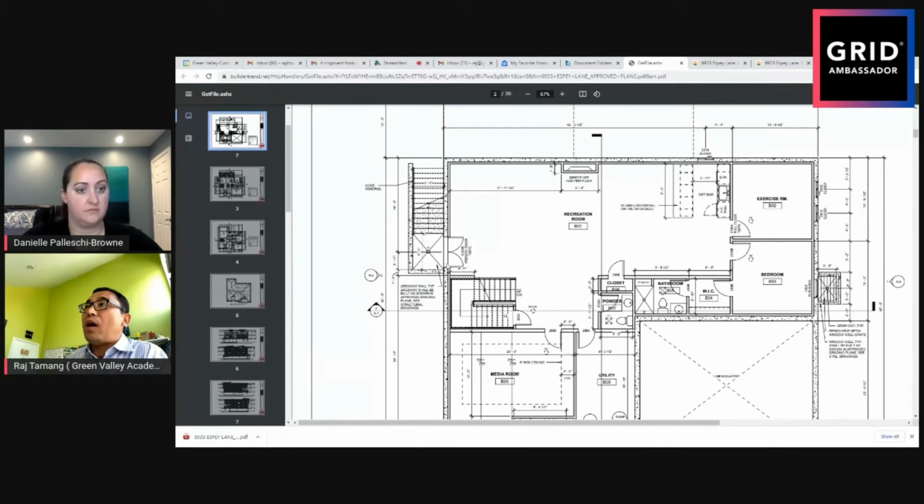And also, something you have to remember, a concrete wall opening versus a stud wall opening is a little bit different. We can go into more detail next time. But quickly, if you have a concrete wall opening, you have a regular door, but you have to think about how you're going to attach the door to the concrete wall, right? Because upstairs on the first floor and second floor, it's a stud wall. You can nail it, you can screw it, whatever you can do. But here, you cannot just go and screw into the concrete wall. It's not that easy, right? So you have to think it through when you design it.